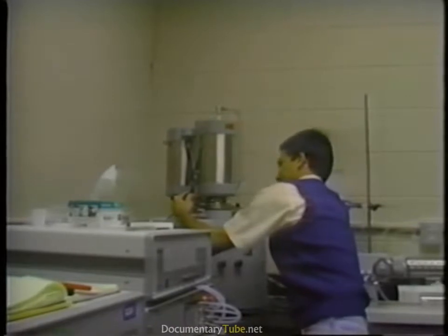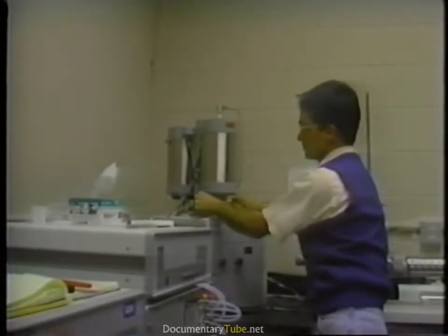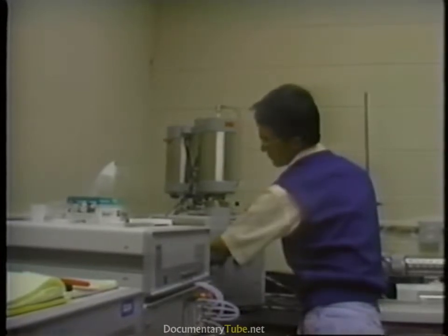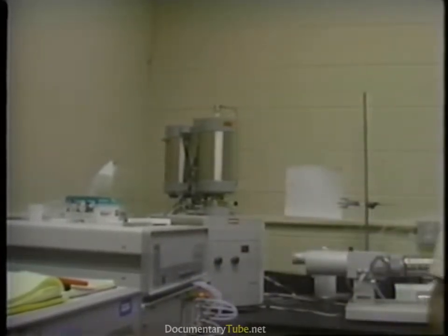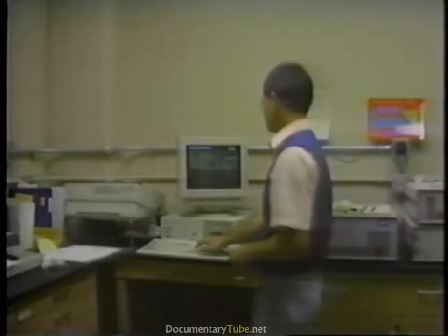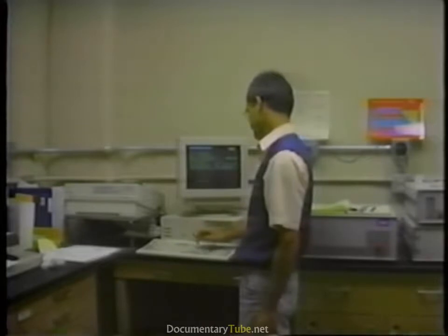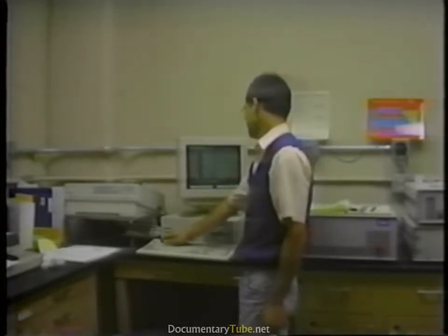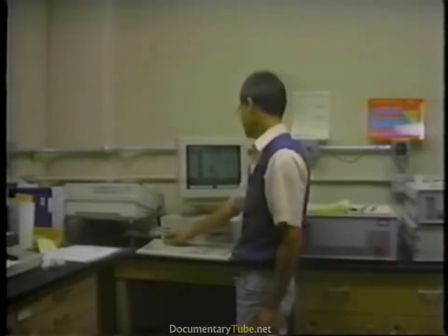The free water in a sample is driven out by heating to 105 degrees Celsius. At 105 degrees, the sample is dry, but still retains its strength. The water involved in the hydration reactions is chemically combined with the cement and can be driven out of the sample by heating to 1,000 degrees. At 1,000 degrees, all of the original mix water has been removed from the sample.